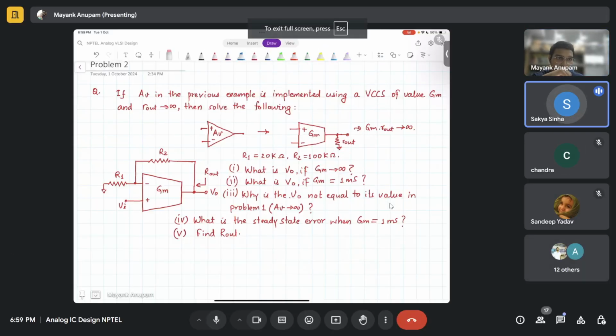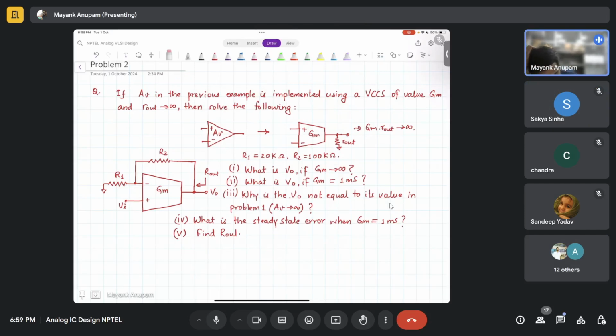Can you repeat again, please? Yeah. So I was saying that we know from our previous question that the first priority which we have from our op amp, this guy, is what? Its gain should be equal to infinity, right? DC gain has to be infinity. Only then will this behave like an ideal op amp.